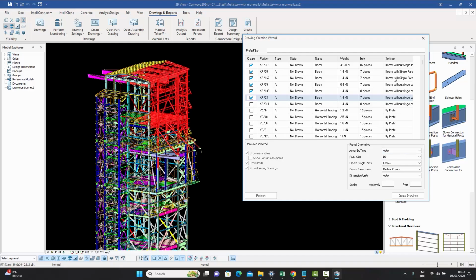For example, these settings would all be done saying that the dimensions would be done using the SI units. But in this particular project, I want to use imperial units. So I'll just say, okay, whatever those settings are saying, when it comes to dimensioning, use imperial units. So I've got these overrides as well.